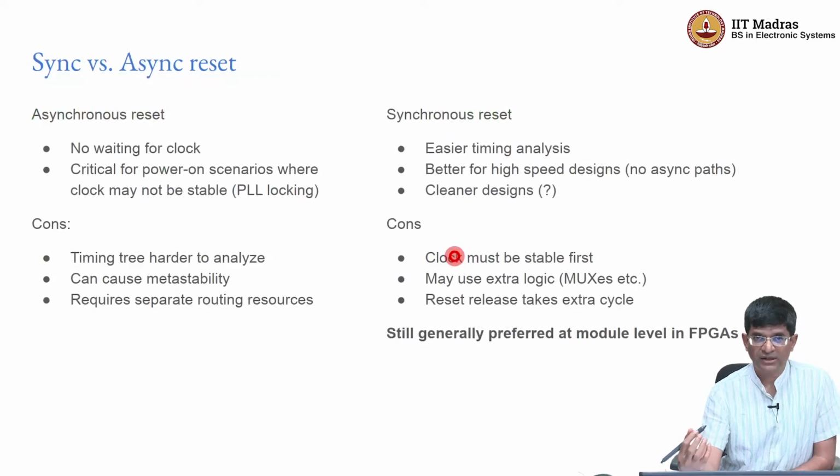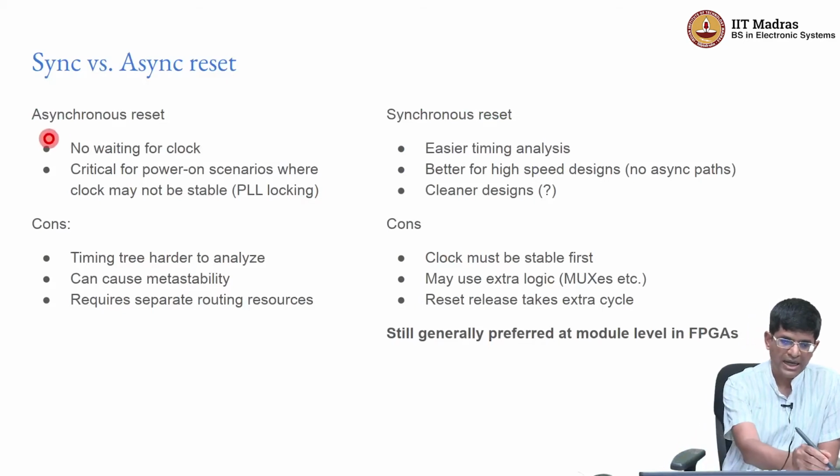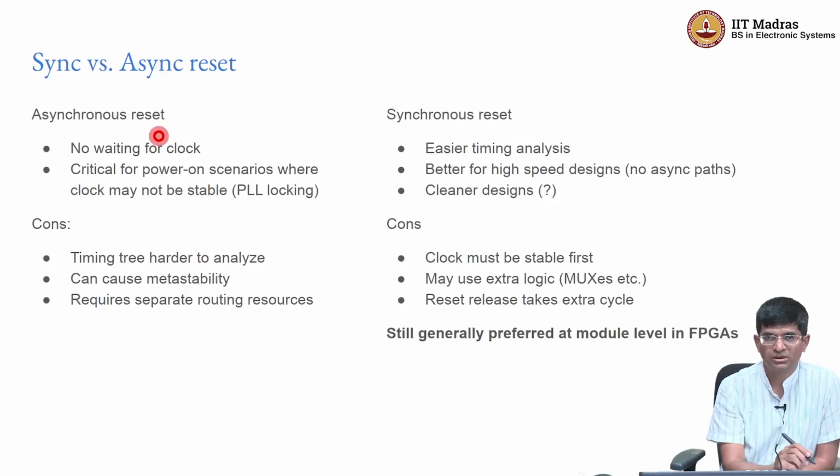Now, I've talked a couple of times about synchronous versus asynchronous reset. I just want to say a little bit more about that. As you can imagine, in the asynchronous reset, we do not need to wait for the clock, right? What we are saying is any time that the reset signal comes in, it overrides whatever is the present state of the flip-flop and just forces it usually to 0, although you could have a sort of set or reset. So instead of a reset to 0, you might potentially have a scenario where you are actually forcing it to 1 under the reset conditions.